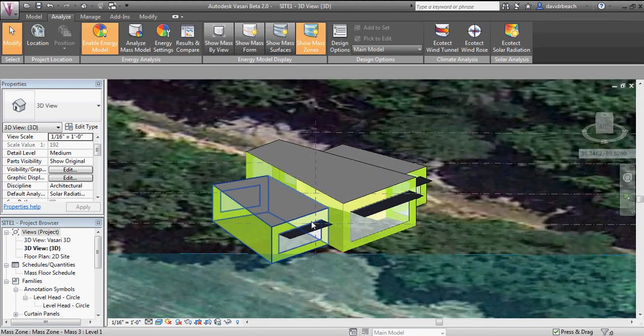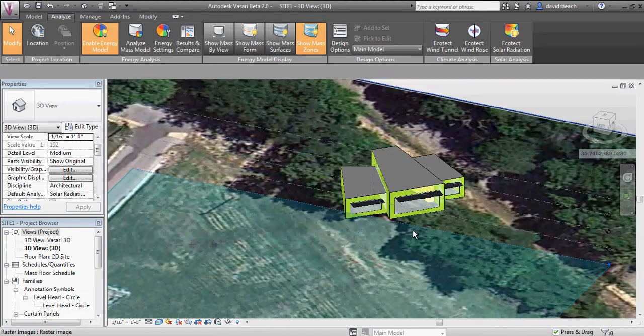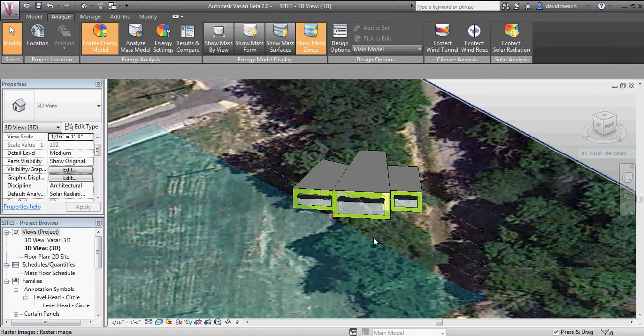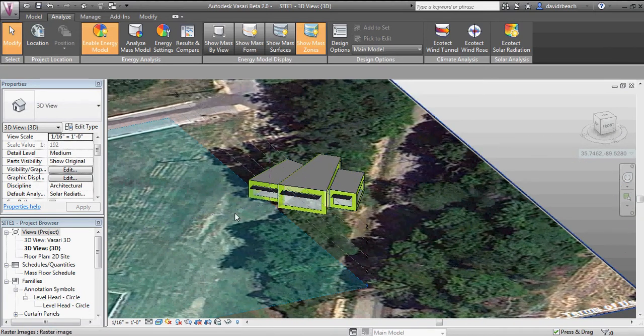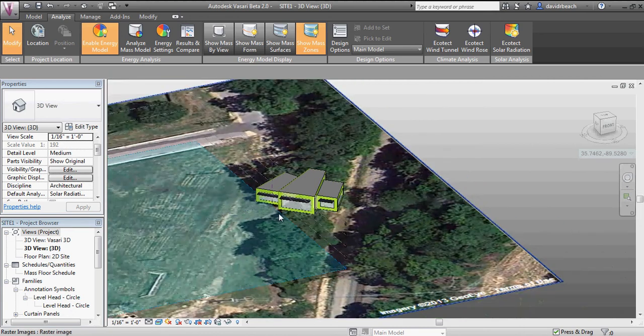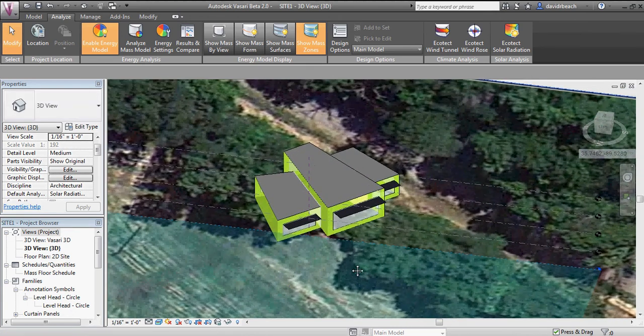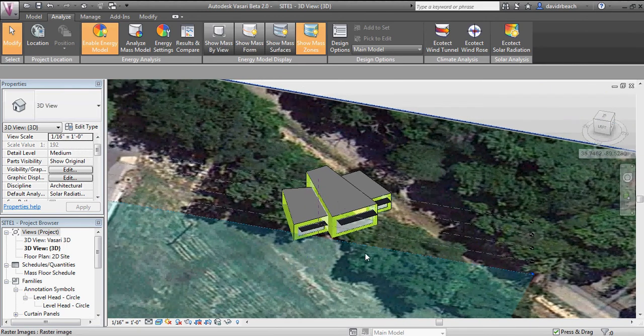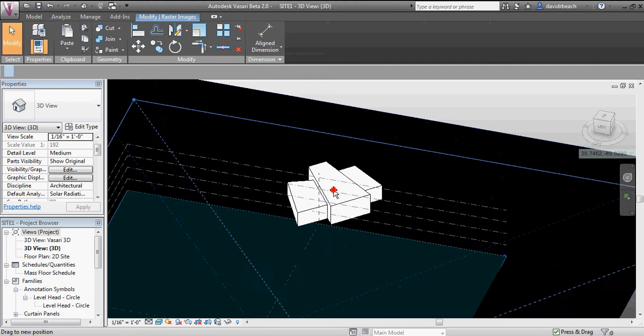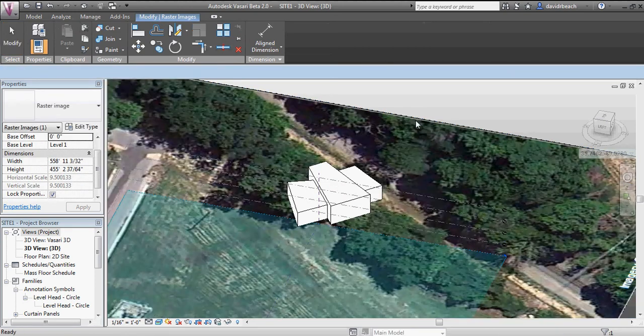While that's going, for the other types of changes that you can make on something like this, I'm curious whether I could take this building and rotate it around. So these particular pieces of glass, rather than facing south-southwest, which we know is fairly intense sun, maybe I can get those more south-southeast. To make that kind of change, I'm actually going to need to go all the way back to the mass form. I don't want to move the site around.